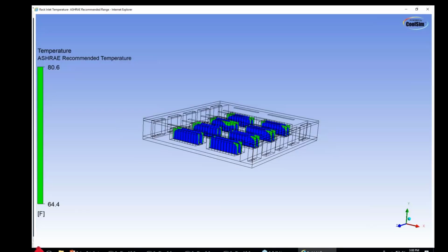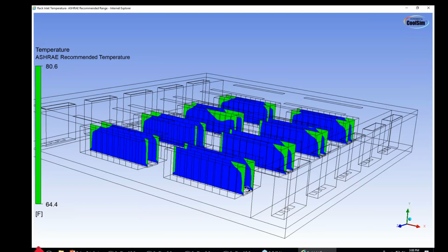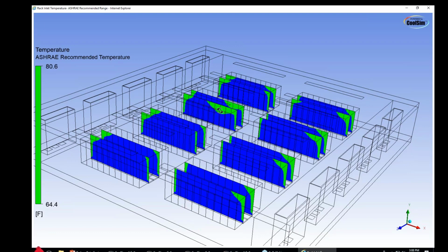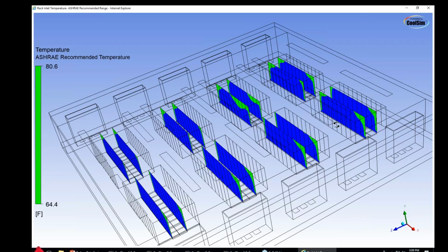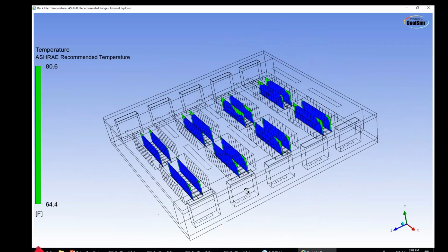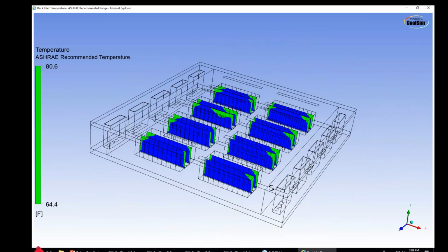And that's a very normal plot of temperature associated. Now this one, I was cutting down the RTI a little too hard. But you see where it turns up. It turns up on the edges. So putting your sensors up high on a design that's raised floor where the cold air is coming from the floor, probably get away with fewer. Probably don't need them down low. So you might be able to get away with just 1 per rack along the top if I were to try to save money. That's what I would do.